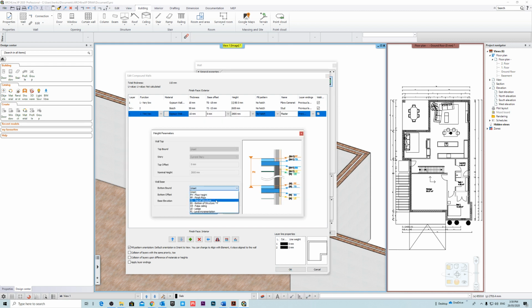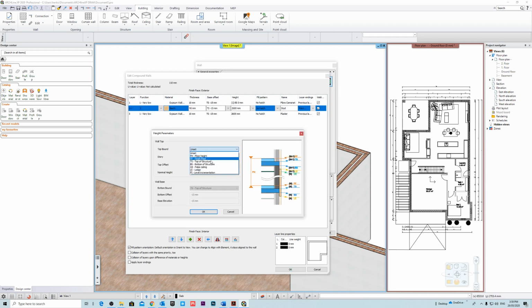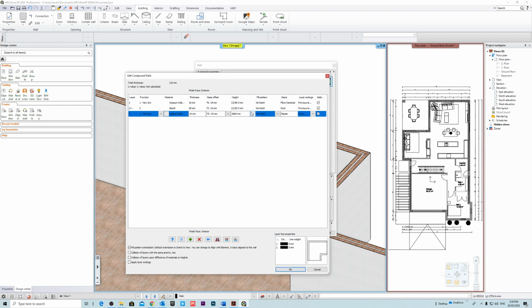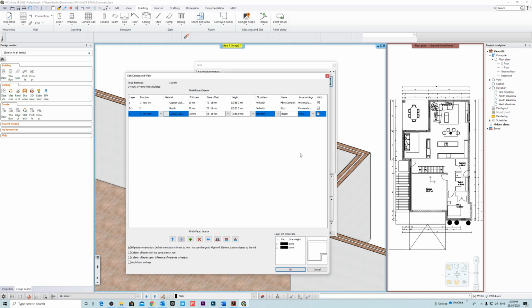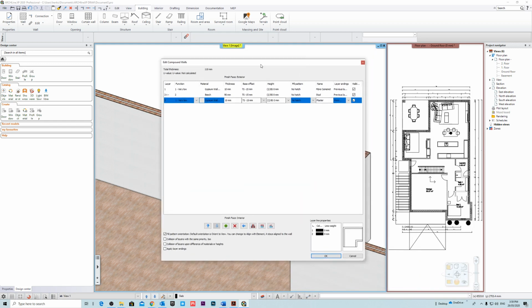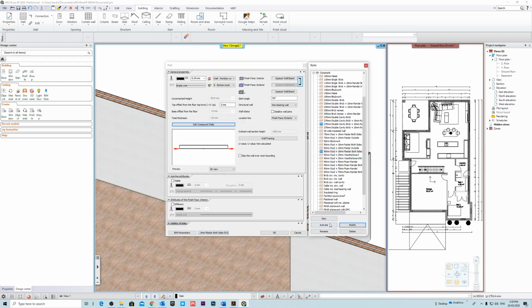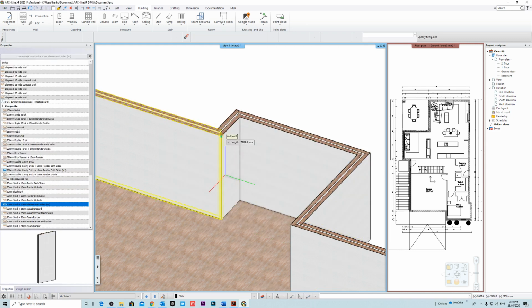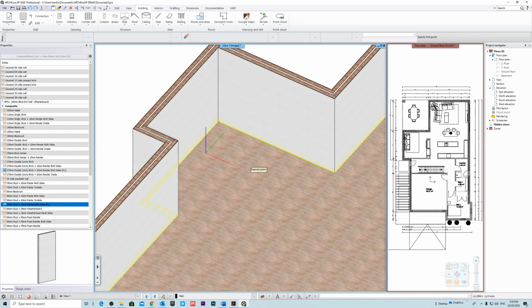Top of structure, minus 15. We'll go here to the top height and make all of these the same. It's quite vital to check your walls when you've created one, to make sure you've constrained all the layers, not just one. So I'll go OK, modify, overwrite it, click activate, and OK. Now if we create our wall from here to here, we'll see that it's constrained.